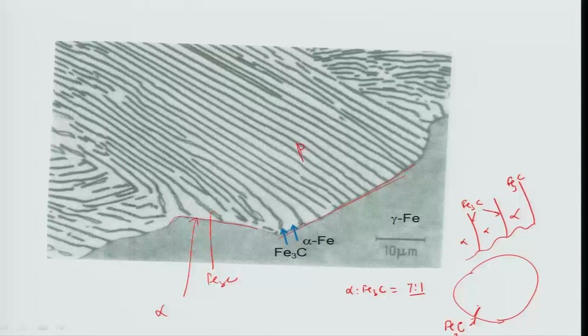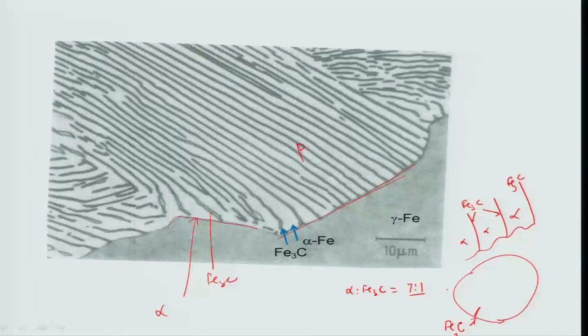As you know, Fe3C contains about 6.678% of carbon, which is much larger than the carbon concentration of the austenite grains for the eutectoid steel, that is 0.8%. So, this whole grain would have a carbon concentration of about 0.8 percent, but the cementite which has just formed inside this austenite grain has a carbon concentration of 6.68% carbon.